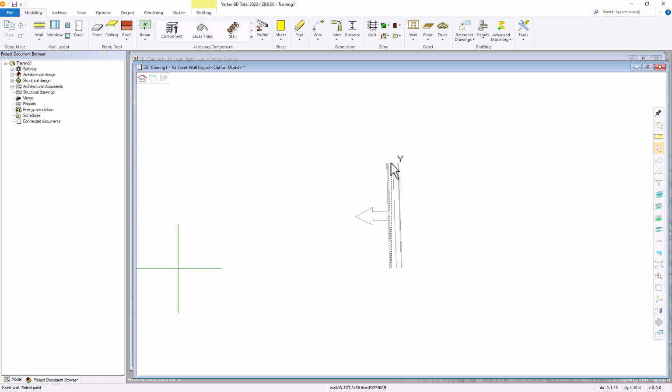Let's go ahead and draw our first wall segment. We're going to add some walls using the X and Y coordinate system. So in this case, we want to go up in the vertical direction, which is the Y axis. So in that direction, we're going to go 20 feet in this example, but we don't want to go in the X direction. We just want to go straight vertical. So in the X, anytime we start typing our distances, it always populates the X field first. So we know we're not going to go in the X direction.